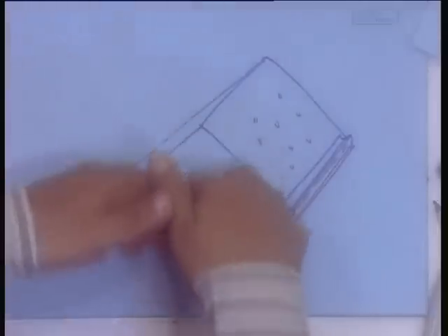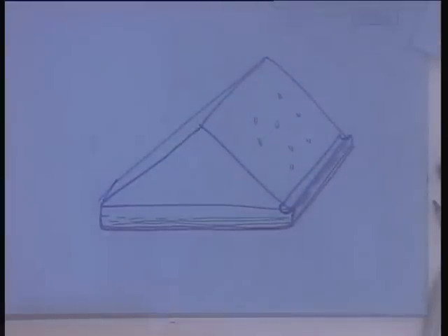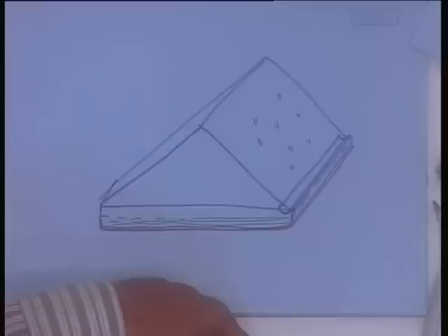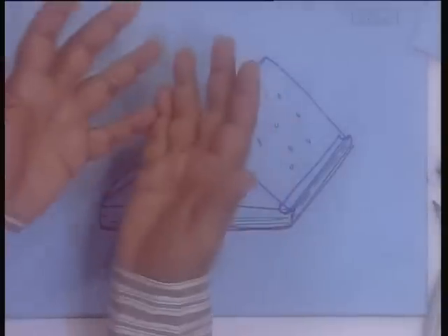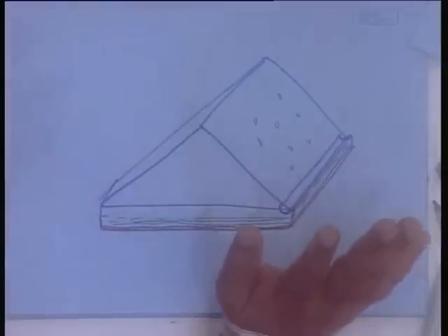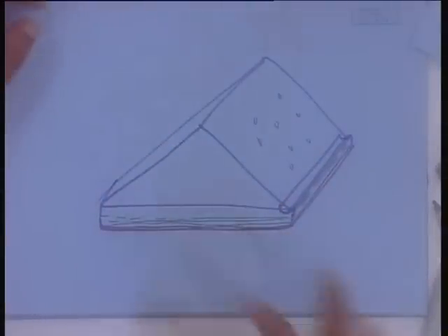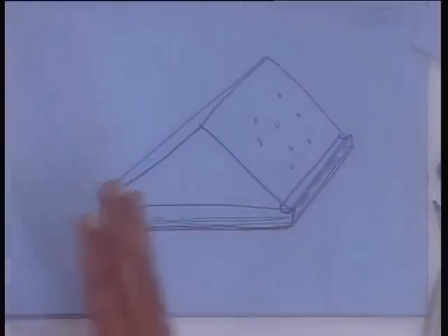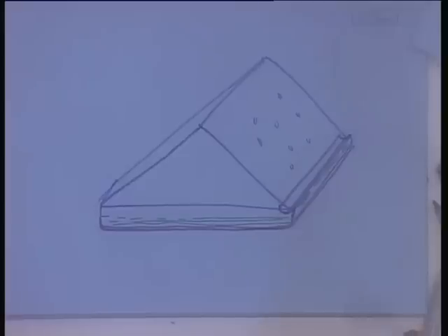During the daytime, the heat will go in, because heat will be conducted towards the ground. But during the night time, the same heat will come out. As a result, the heat is not lost really. The heat that is going in will come out during the night, and that will take part in the evaporation that also continues during the night. So, you can have a relatively longer period of evaporation. So, it is not necessary to spend money in this kind of design on putting a proper insulation. If you do not have any insulation, then also it works as good.